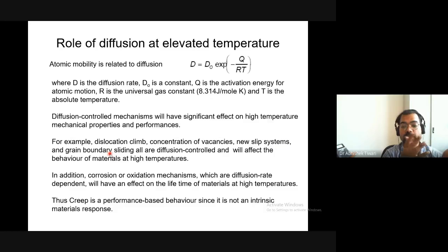So the flow, we know that even at room temperature, the substitutional atoms and the interstitial atoms are always diffusing, but substitutional atoms also have a higher diffusivity at the grain boundary, because they do not have to necessarily find a vacancy next to them so that they can diffuse, right? Because in the grain boundary there is no requirement of having an atomic site, and so a vacancy is not required so that you can move. The atom can move very easily, so the diffusion is very high on the grain boundary already.